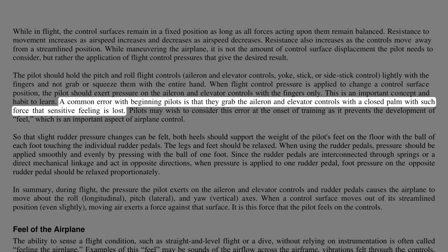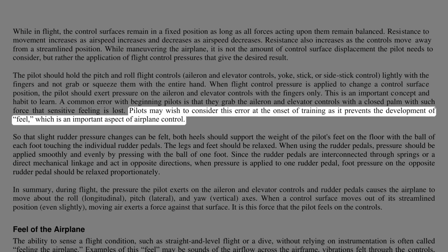A common error with beginning pilots is that they grab the aileron and elevator controls with a closed palm with such force that sensitive feeling is lost. Pilots may wish to consider this error at the onset of training as it prevents the development of feel, which is an important aspect of airplane control.